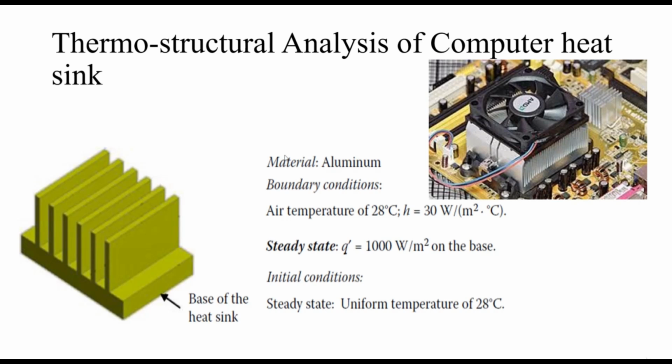To perform a thermostructural analysis of a computer heatsink. This particular computer heatsink is made out of aluminum material, and these are the different boundary conditions that we need to apply on this particular heatsink, and then we need to find out the temperature distribution inside this heatsink. And once we find out the temperature distribution, then we need to find out the stresses that are going to arise due to the application of these thermal conditions on this particular heatsink using thermostructural analysis inside ANSYS Workbench.